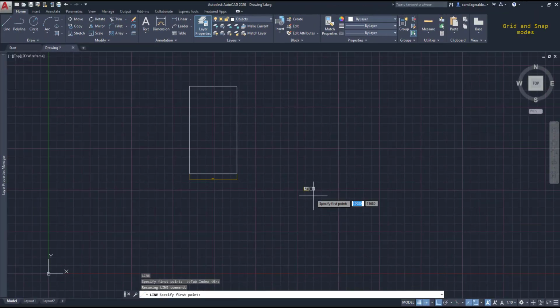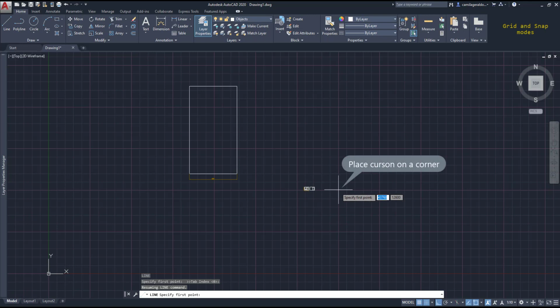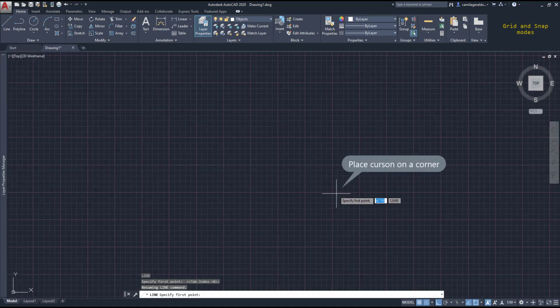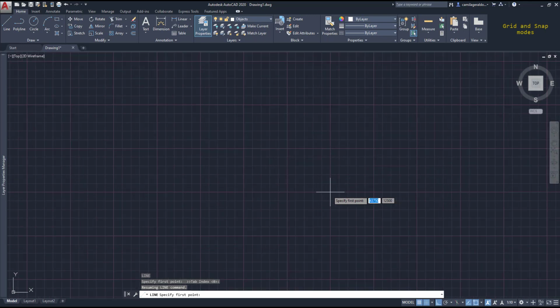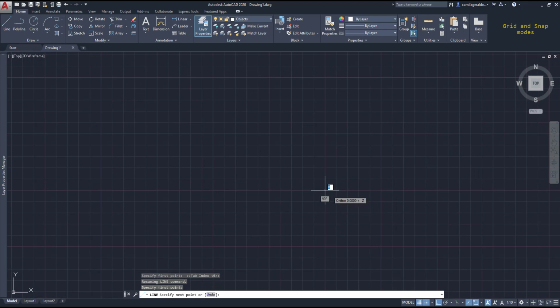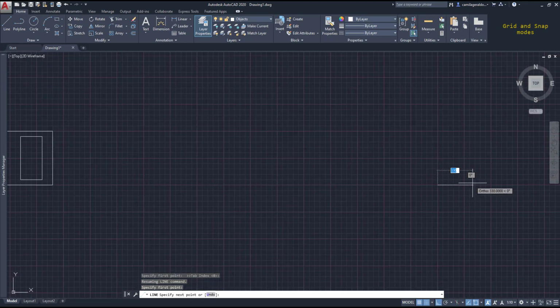If I like to have the workspace more organized and I want a point to be in the corner of an intersection when I zoom out a lot, like where I am now, simple, place the cursor there, in the corner, and zoom in slowly, keeping the cursor in the same position. When the grid doesn't resize anymore, it means that the grid is now resized correctly.